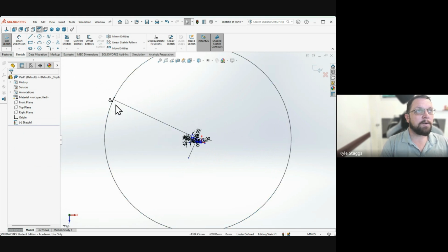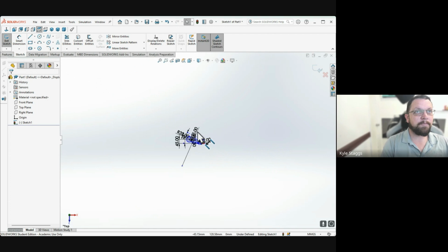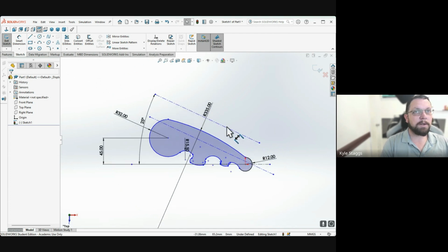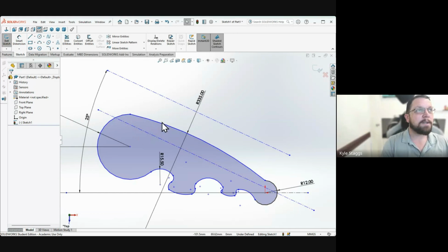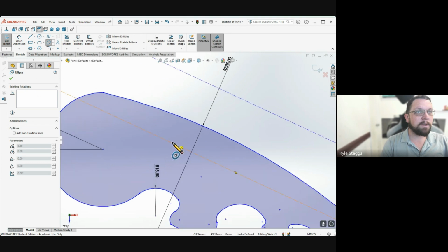What you can then do is select that dimension and hit delete. This is one of the secrets of this particular project, being able to move an object around and then delete that dimension so that it stays where it is. And then you can add something like an ellipse or a slot, should you have to do such a thing.